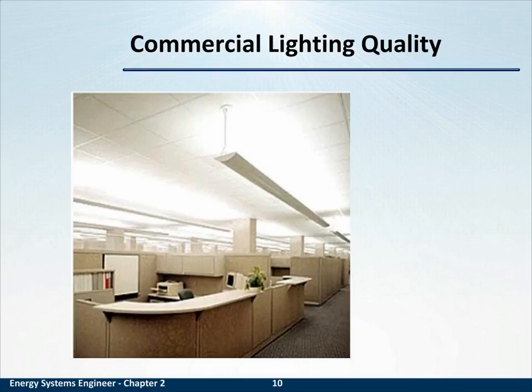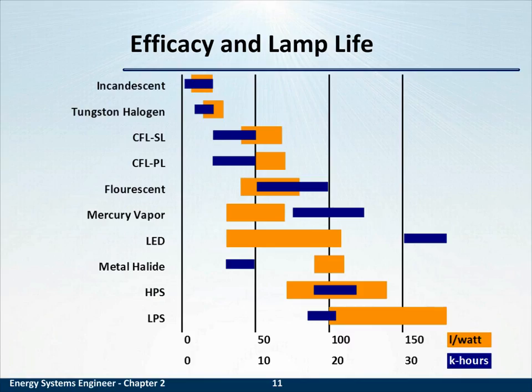Or where you can't get light, such as an under cabinet, you put in a small under cabinet light. However, glare is difficult because of the computers present in most office spaces. So what this designer has done is use a reflected up light that is bounced back off of the white ceiling and diffused into the room. Just one example of an intelligent lighting design.